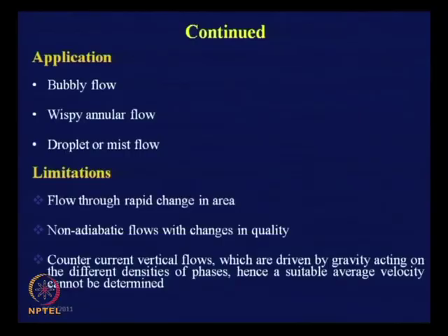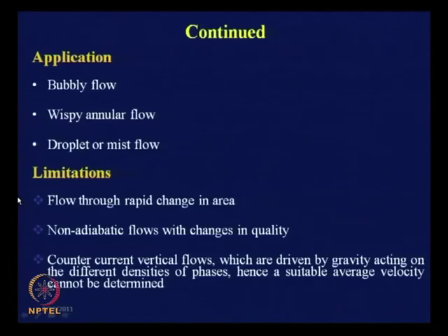Under this rapid acceleration, we cannot have the two phase flow situation. This I have already written down here. So, this is one thing where we cannot use it, and for the rapid acceleration, what is the problem? Let the two phases accelerate. Why can we not use it? Because under such circumstances there is a drastic change in pressure. The moment there is a drastic change in pressure, flashing occurs. The moment flashing occurs, thermodynamic equilibrium is no longer valid. Clear to all of you?